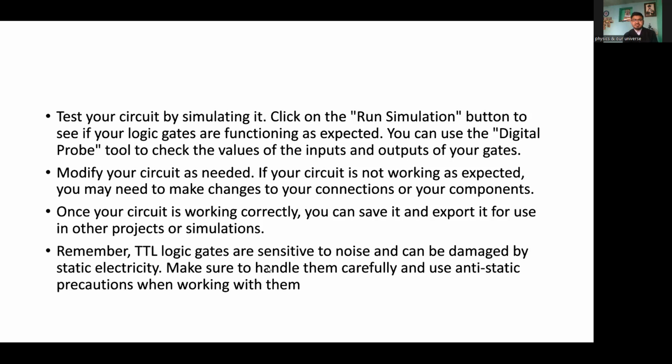TTL logic is sensitive to noise and can be damaged by static electricity. Make sure you handle them carefully and take anti-static precautions while working with them.